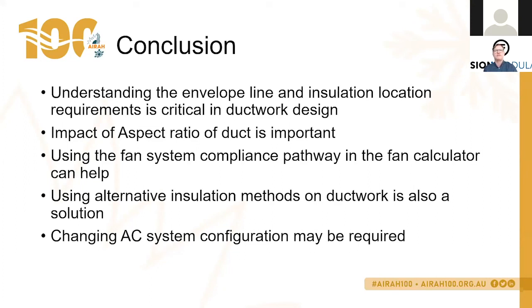You may have 5 supply points into a room, you hard duct to that room, and then you've got 6 metres of flex to each one of those supply points in that room. But it's 6 metres maximum on any duct run, so from the supply point back to the air handler. Same answer, 6 metres. And there's no difference in the insulation requirement, whether you do a 3 metre piece of flex or a 6 metre piece of flex.